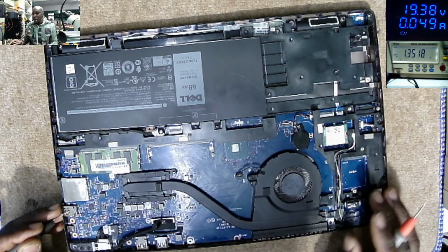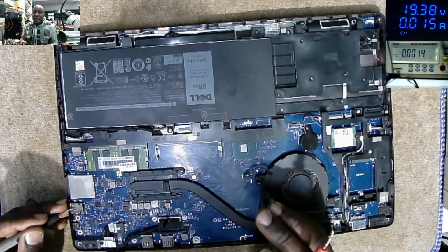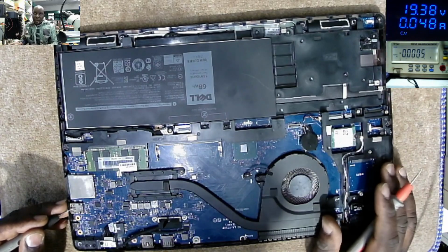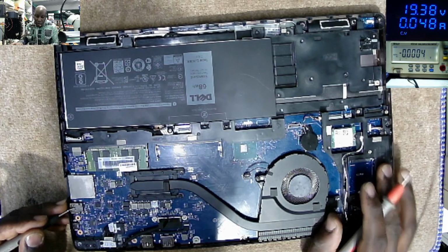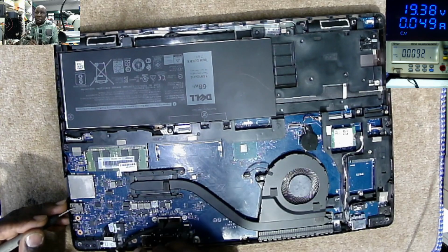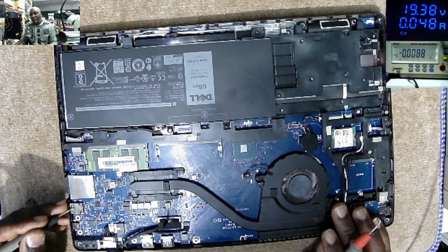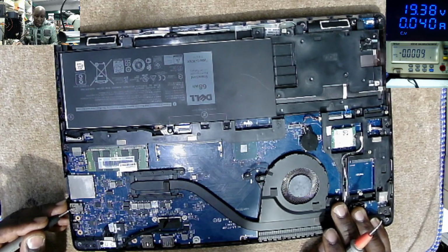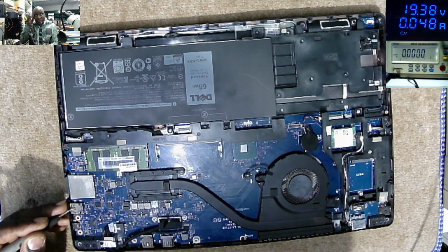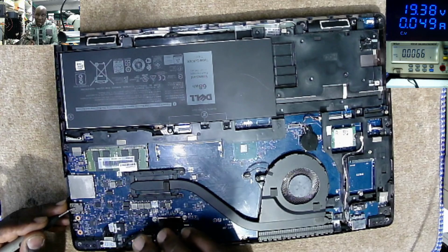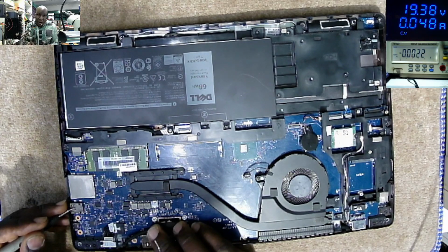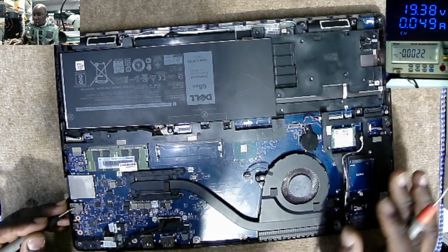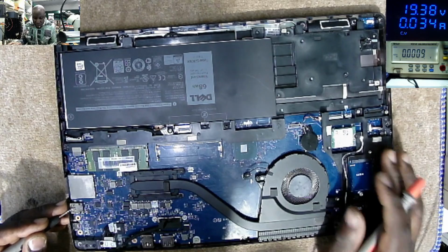So what I believe is this is the new model. If I see 13.5, I know that the PD controller is working. You know, in the new models we have the input MOSFETs and an independent power supply, which generates the main 19 volts power rail and is controlled by a PD controller. And I know that we have 13 volts, which is the main power rail, and the 19 volts is being stepped down to 13.5 volts. So the PD controller is working fine.